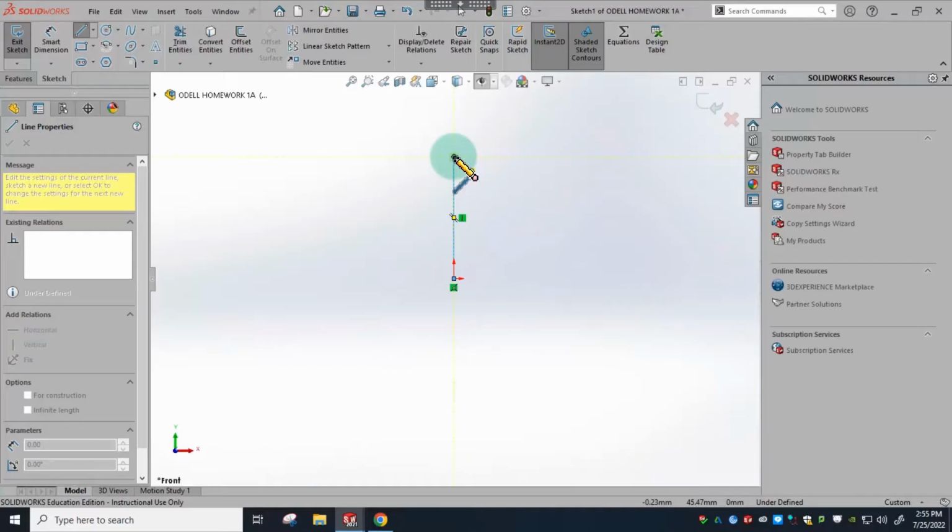So I'm going to left click. Now, I only clicked once. I can go ahead and make another line without doing anything else. I'm going to do the same thing. If you notice, these little yellow dotted lines indicate horizontal and vertical to help you draw a nice square. So I'm going to do the same thing. Click. Now right here, I don't want a straight line because we want a little chamfer on this part. It doesn't matter if you click up here or down here, just don't let it snap to one of these yellow lines. So right here is fine.